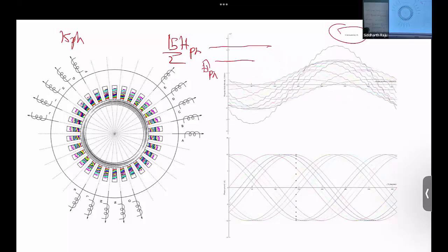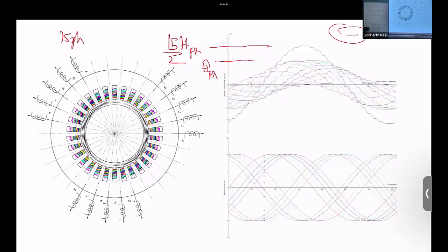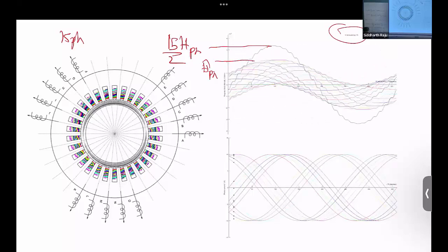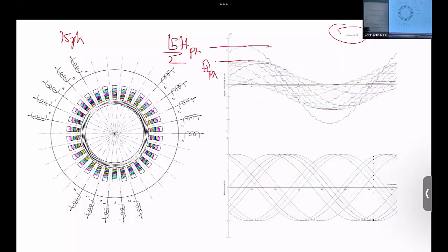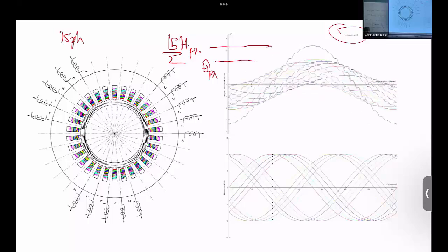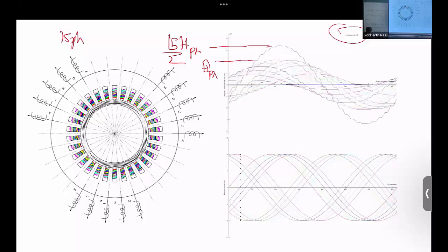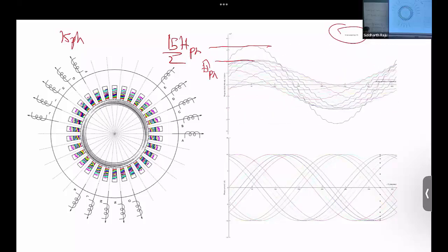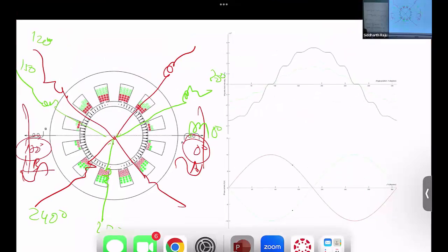Right? Again, when you have a 15-phase motor, you have multiple options. You can take 360 degrees, divide by 15 and spread the windings evenly. Or you could do groupings of 3 and 5. Here I've done groupings of 3, 5. Or you can have groupings of 5, 3. So there are too many options in which you can wind these motors, and each has different harmonic cancellations that you can achieve depending on how you wind them. Right? Any questions? Okay. So for any polyphase motor, any phase greater than 1, the motor will start rotating. That's the idea that you need to take from this.